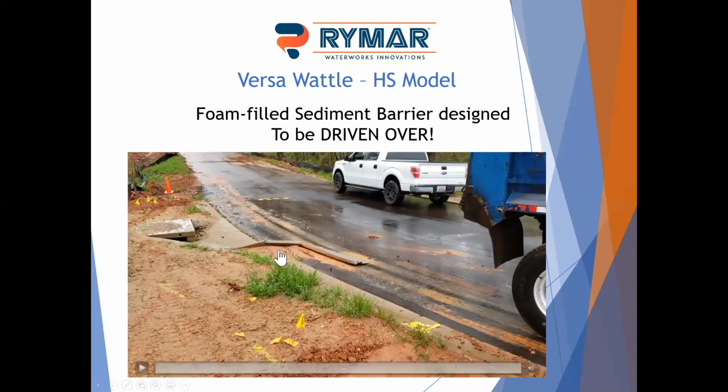But with some normal maintenance, ease of maintenance, they work very well, particularly when you have this lip on the curb. Now, they're also excellent if you have a construction entrance that is sloping towards your main roadway, and you need something across there. Obviously you don't want to put silt fence or something that can't be driven over to block access. So if you need to maintain access on any hard surface, they're designed to be driven over multiple times and continue to work.